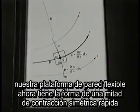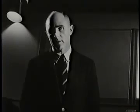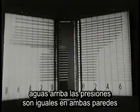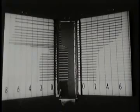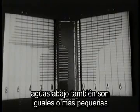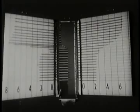Our flexible wall rig now is in the form of half of a rapid symmetrical contraction. Upstream, the pressures are equal on both walls. Downstream, they are also equal, but lower. Because of the area decrease, the average velocity increases, and, according to the streamline's equation of motion, the average pressure falls.